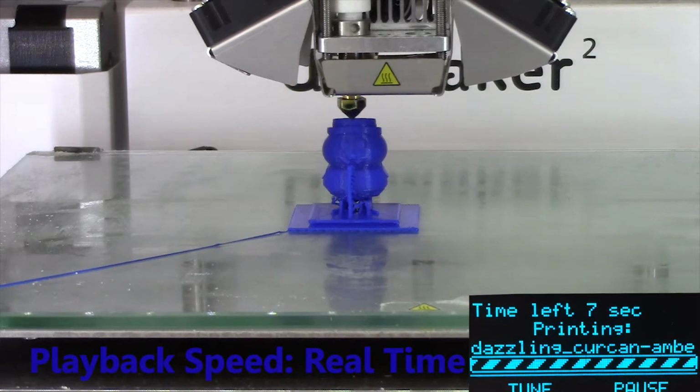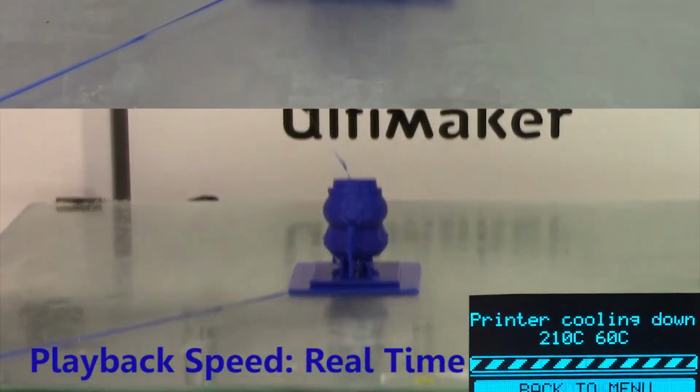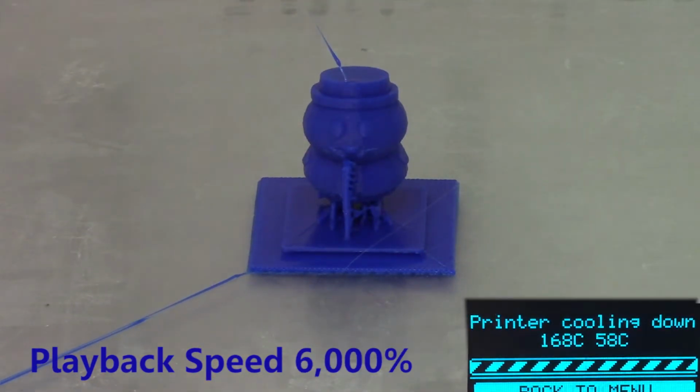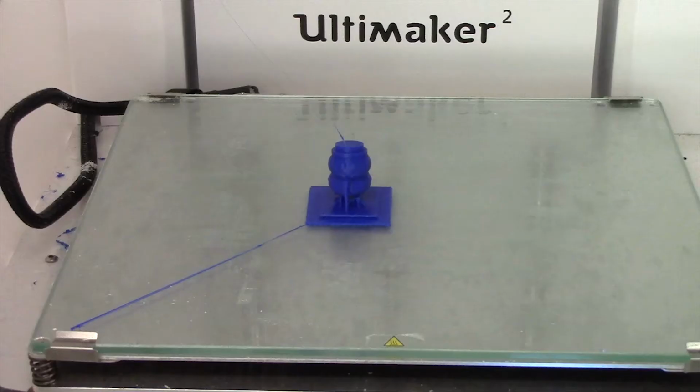And during the last few seconds, you'll see the countdown, and you'll also see a screen indicating that the printer head is cooling down. Now, during this time, unlike other printers, it's recommended that you wait for the cooling process to finish prior to removing the part. Because there's a glass plate on the Ultimaker versus the plastic bottoms of other printers, it's okay to do this, and it will avoid the part warping when you initially try to separate it from the build tray.